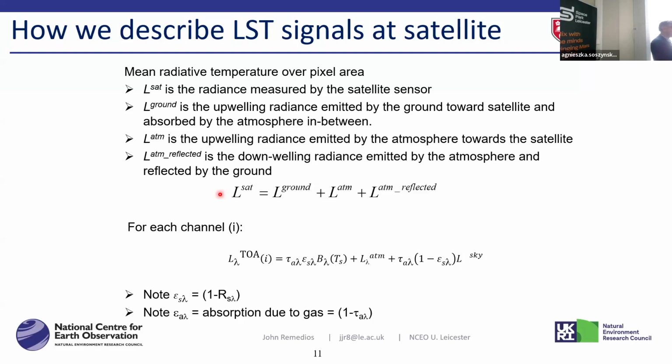It's got to have calibration in it. By looking at a black body, it will have to have some knowledge of the linearity of the detector. It might have to have corrections for stray light. Most instruments are not perfect instruments. They have some components which bring in radiation that we do not expect to see. There's a host of effects that might go on, and if you want to do a truly accurate measurement, then you ought to trace through all those in a quantitative fashion. Fortunately, we don't have to do that.